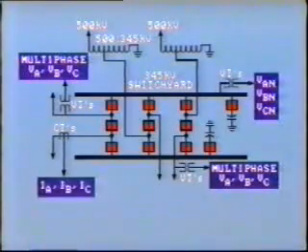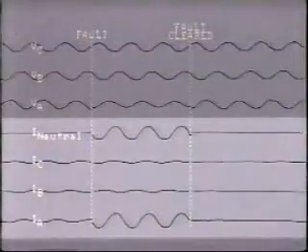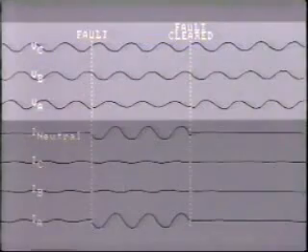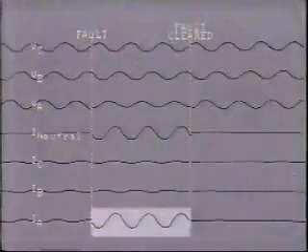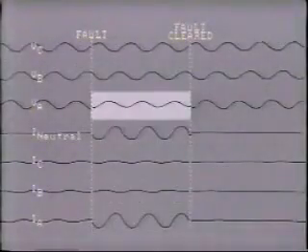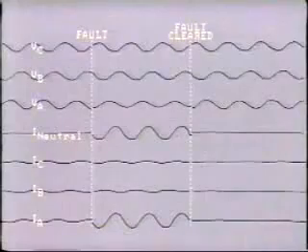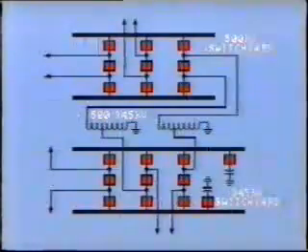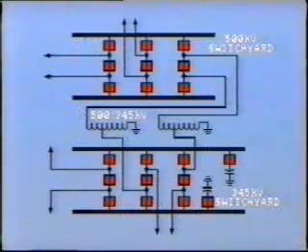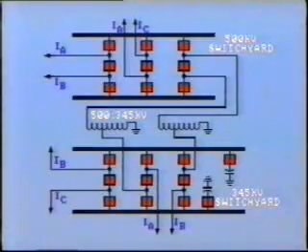It's also important to look at phase current in each transmission line. The current traces can then be compared with voltage traces to confirm which phase or phases were faulted. A sharp rise in current and drop in voltage on A phase, for example, is a pretty sure sign of an A phase fault. Often there are not enough channels to monitor each phase current of every important line. So, quite often, only one phase of each line is monitored, with the phases alternating from one line to another.